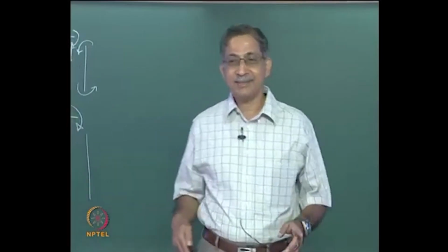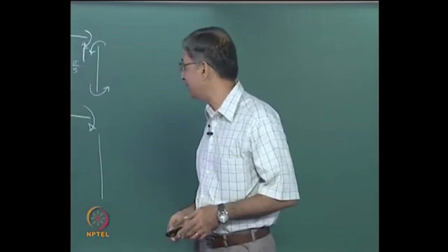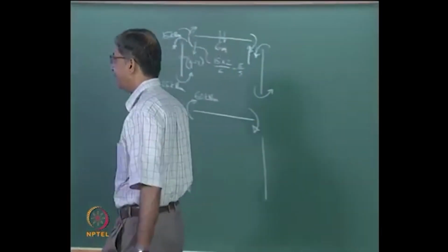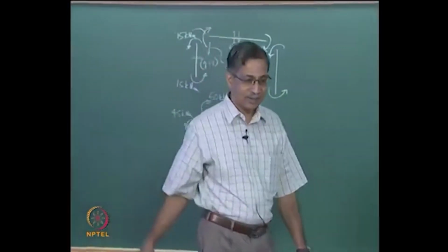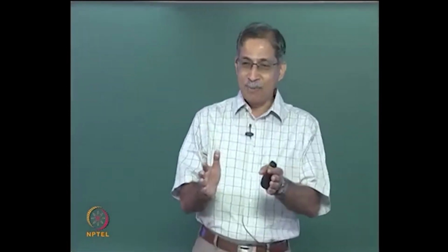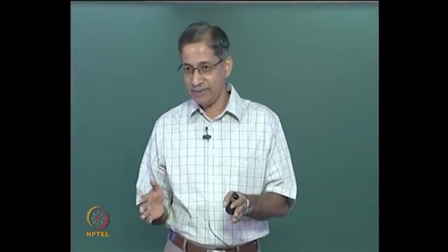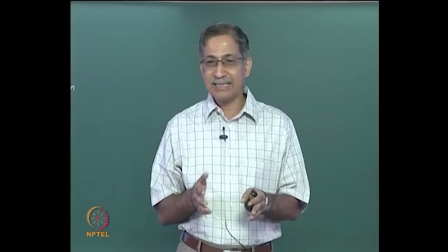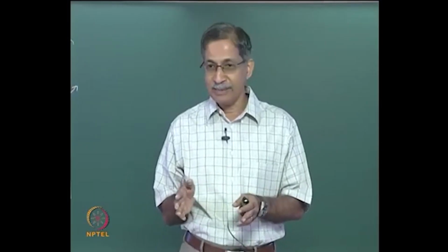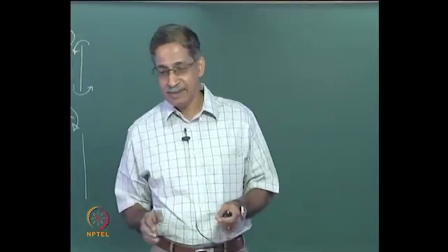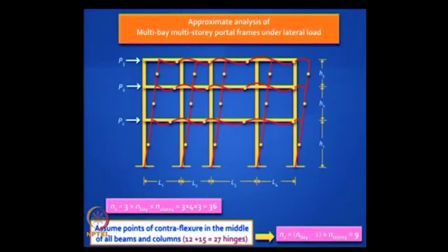Okay, so that's your method. You are saying that the total load is shared in proportion to the average bay width. So the exterior columns end up with less column shear than the interior columns, right? That was one proposal, but the one which gained more acceptance was one which made it simple. It says let the exterior columns take half the shear of the interior columns, okay, and that is one way of doing it.